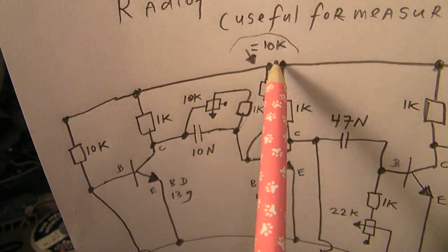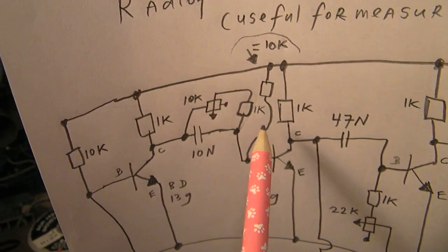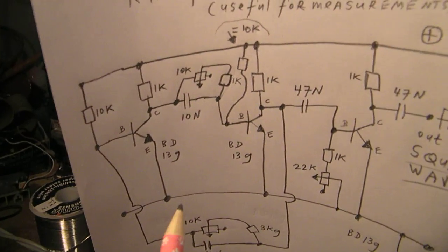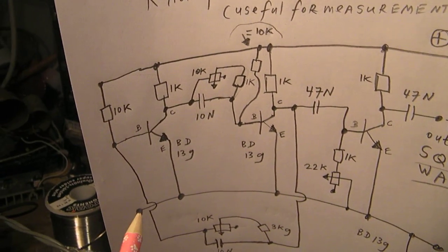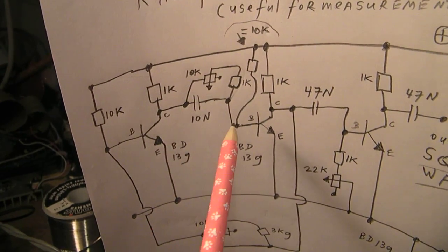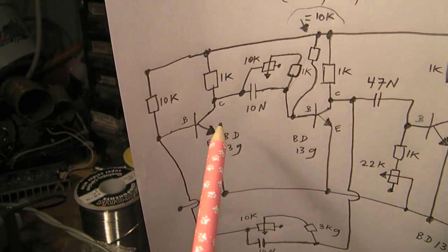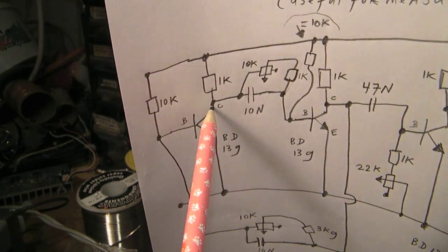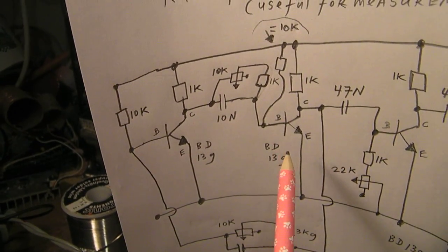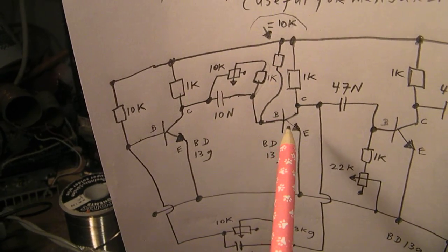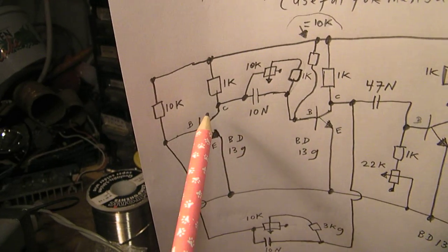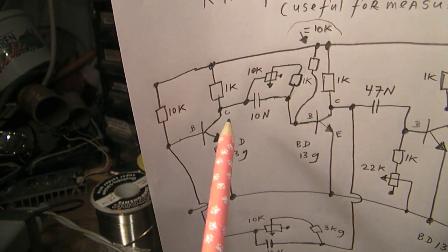Not very clearly visible, but anyway. And then these two transistors are made to oscillate by a frequency dependent network between the collector lead from the first and the base from the second transistor. The base is the sensitive electrode and the collector is in general the output electrode.